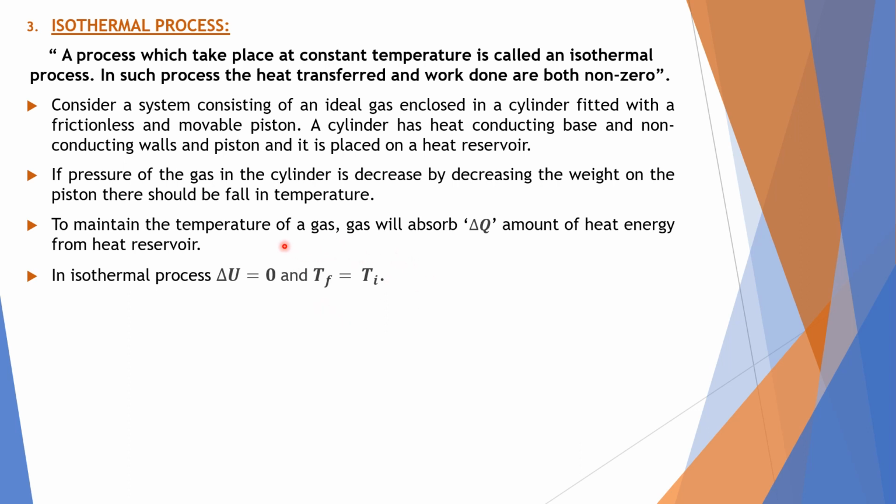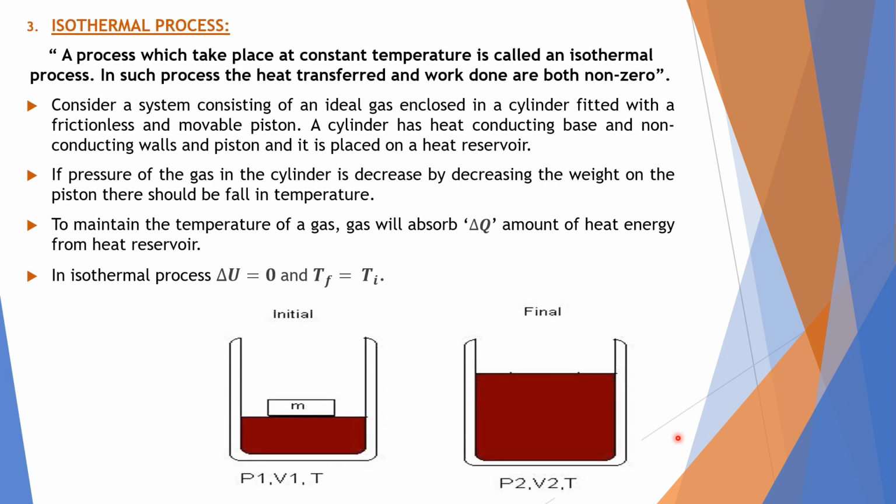And if the temperature of a gas is constant, it means that the change in internal energy is zero. We are not talking about the internal energy of a gas, we are talking about the change in internal energy. So the internal energy of a gas exists, but the change in that energy is zero. So here we have a diagram in which, in the initial stage, we have pressure, volume and T, and if we remove the weight from the piston, the gas will expand, but due to the heat reservoir, the temperature of the gas is constant.